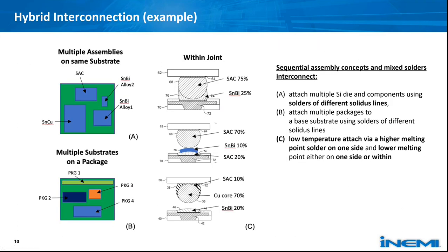Now, before we move on into the details of the execution phases, one note to clarify during this project is this low temp solder between the top die to the base substrate could be comprised of either entire low temp material, such as having, say, tin bismuth on both sides, or it could comprise of having this low temp solder only on one side.